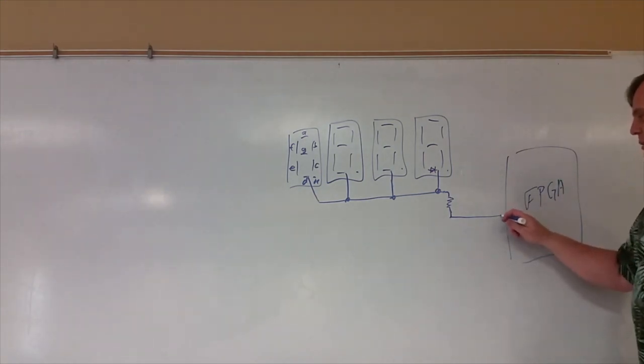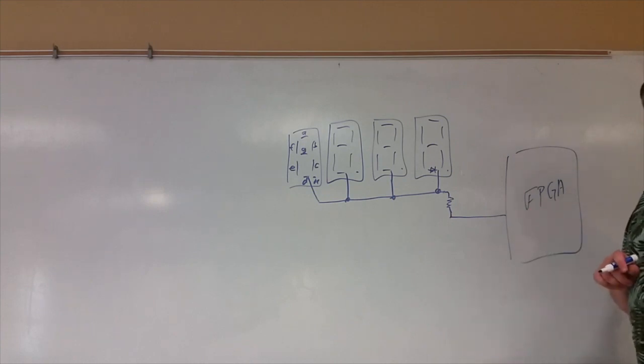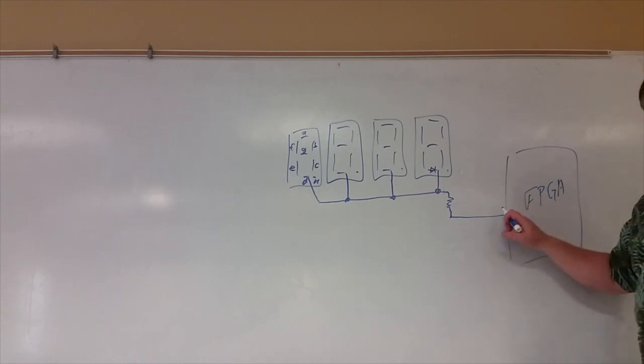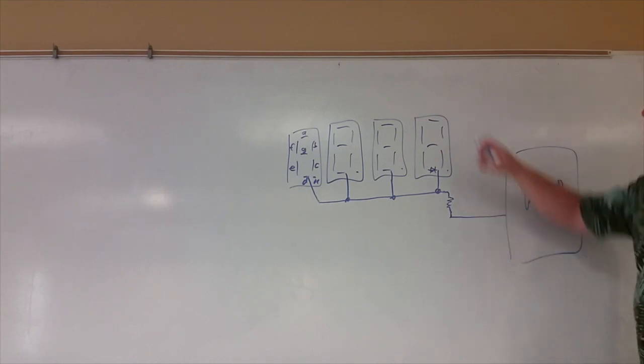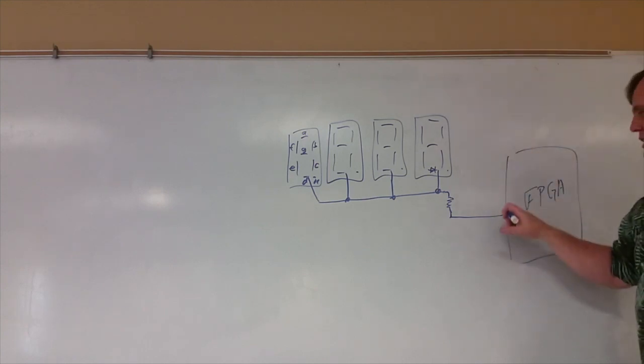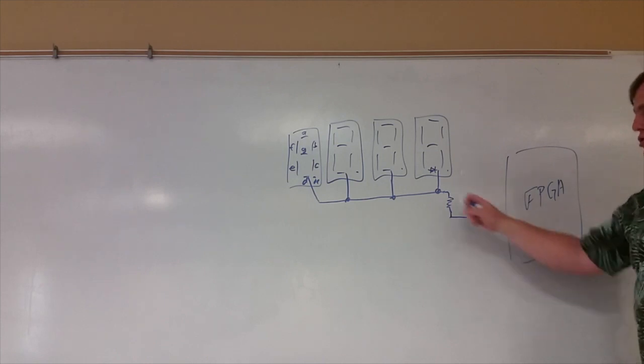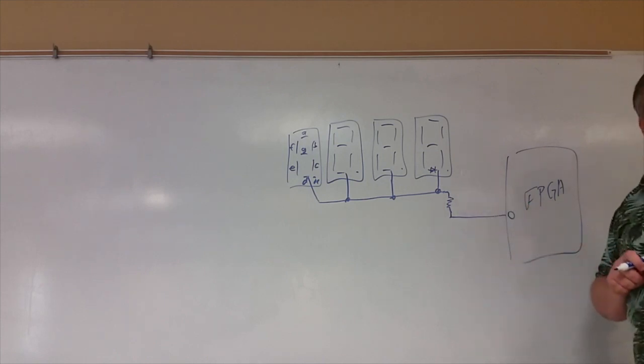So this is going to become an I/O pin. If I write 1 to it, guess what happens? Yeah, because now it's high, there's no sink. So it doesn't matter what voltage you put up there, even if you give it power, it's got power here, there's no current flow. So to turn these on, you have to give it a 0.